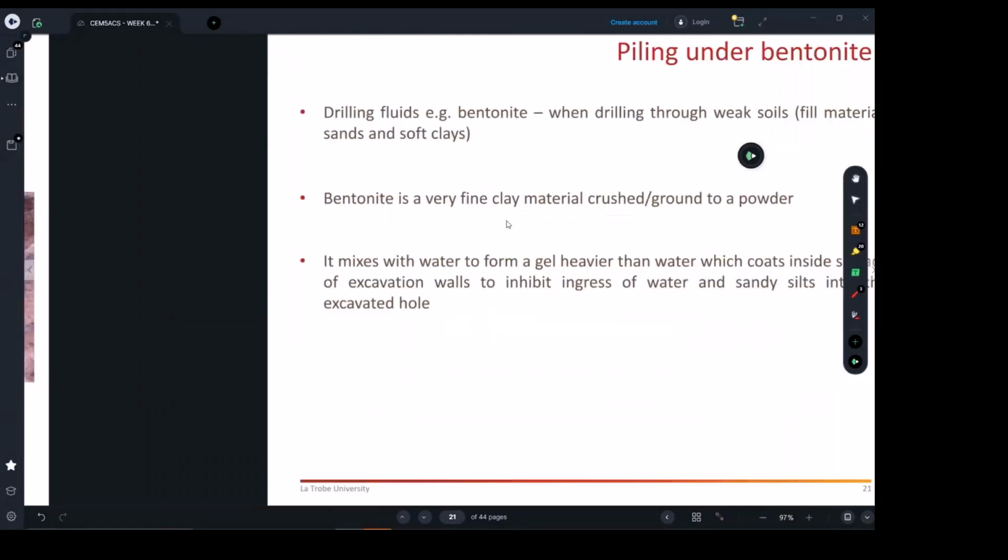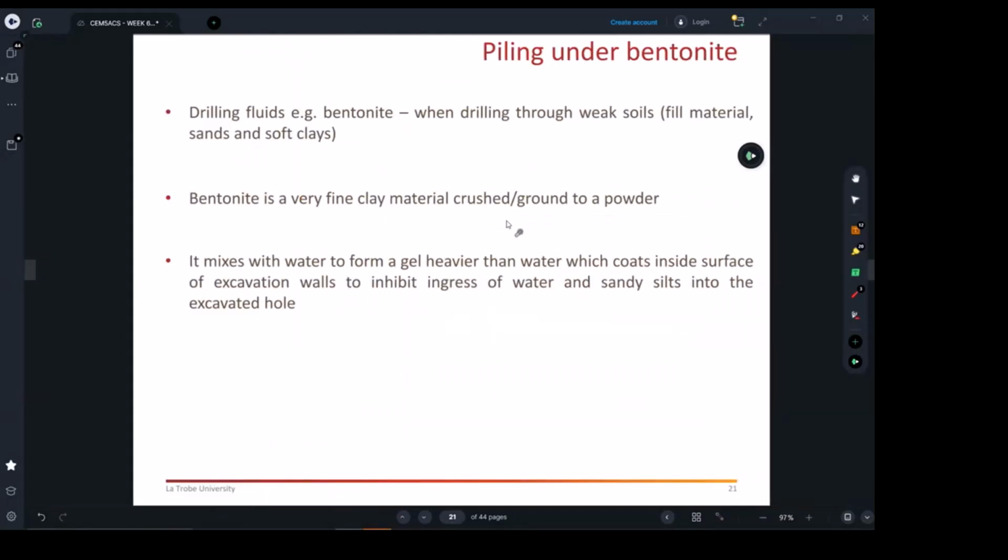Driven piles, the piles we need to nail into the ground, for precast piles. Number two, bored piles, and we said sometimes you can dig the hole, put the cage, pour the concrete. Sometimes the soil is not stable. What you do, you're going to dig the hole, pour the concrete as per the CFA method, then submerge the reinforcement. And we do have some features and details you just need to be aware of, which are clearly stated